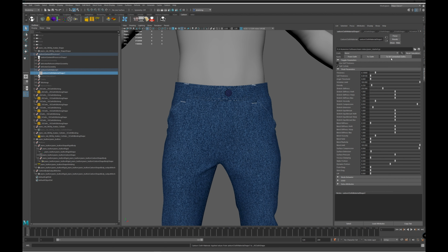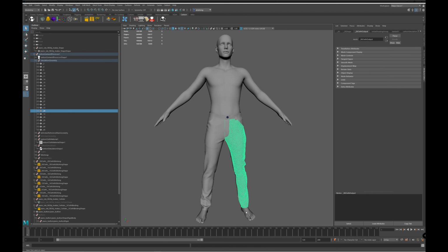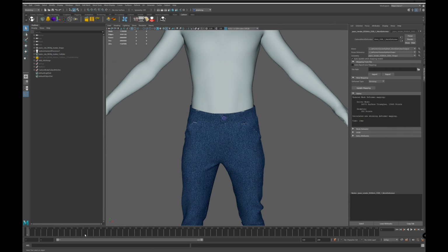These material settings are designed to go with a simulation setting of 10 iterations and 100 subdivisions. This number of subdivisions and iterations is needed because the jean leg panels have 10,000 triangles, and that means a network of several hundred from the top to the bottom of the panel. Okay, let's sim a few frames. It's not going to be super quick because we've got 60k triangles and 1,000 iterations total per frame.